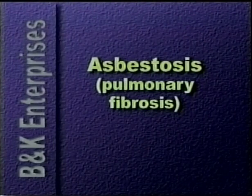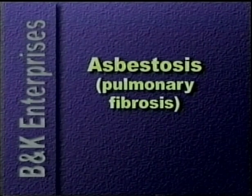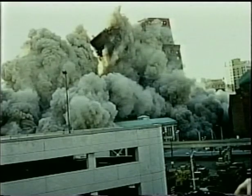The risk of asbestosis is minimal for those who do not work with asbestos. The disease is rarely caused by neighborhood or family exposure. Those who renovate or demolish buildings that contain asbestos may be at significant risk, depending on the nature of the exposure and the precautions taken. There is a direct dose-response relationship to this disease. The disease results after exposure to high concentrations of fibers over a long period of time, measured in years.